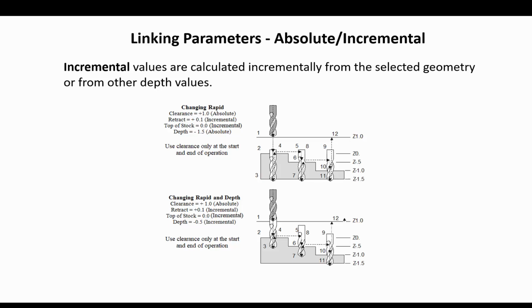The following diagram illustrates two of the most commonly used depth settings. This example is for a drilling toolpath and shows tip compensation active. For a drilling toolpath, the retract height is the height from which the tool feeds into the material. For other milling toolpaths, that is the feed plane.